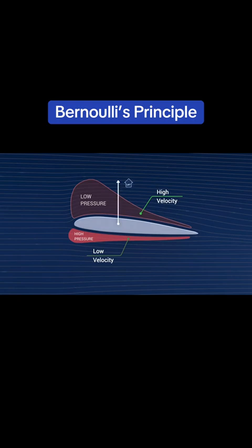Lift arises from the pressure field created by circulation around the airfoil and the downward deflection of airflow, which involves conservation of momentum. Bernoulli helps relate velocity and pressure locally, but it is not a complete explanation of lift by itself.